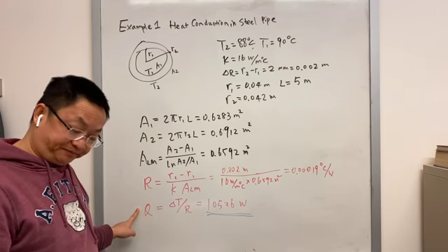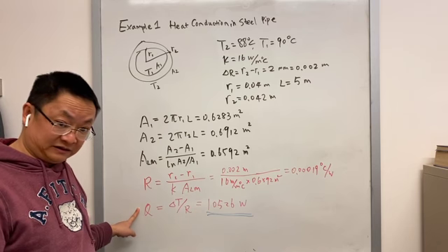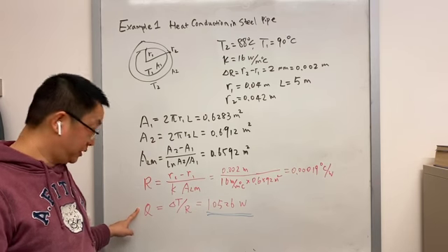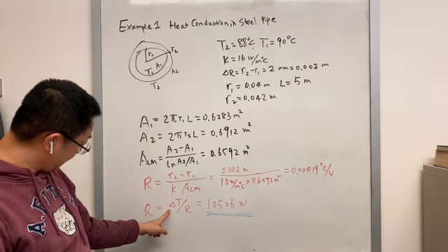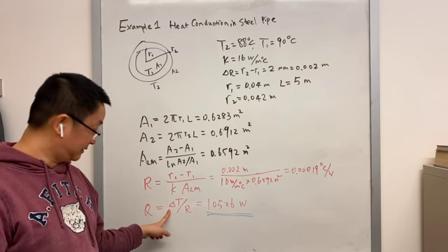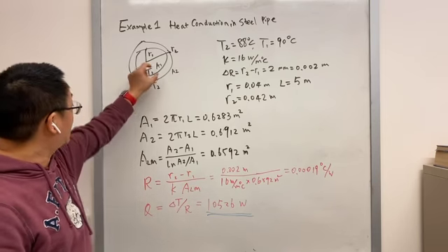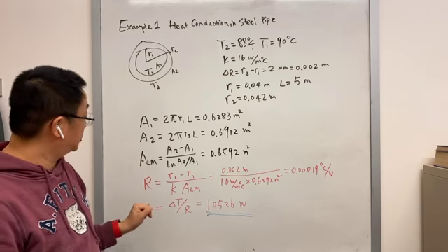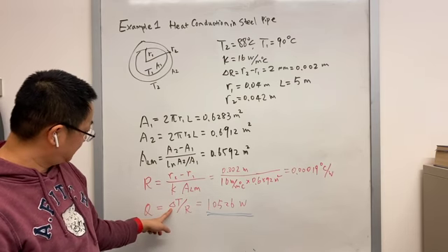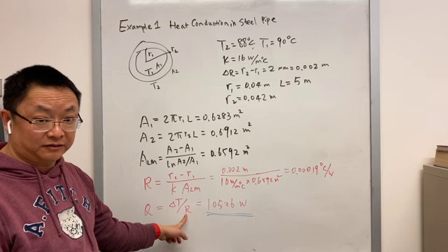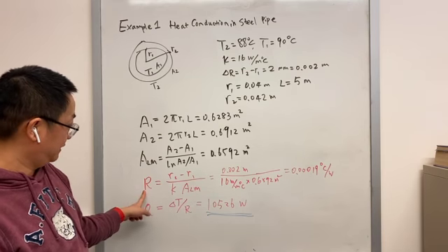As you may recall, as an analogy to electrical circuitry, we take our driving force, which is the temperature difference across our heat conduction material. That will be T1 minus T2, and the thermal resistance we just calculated.